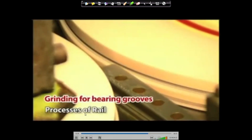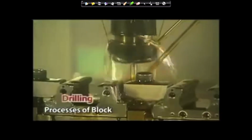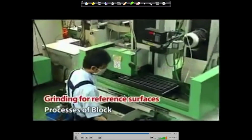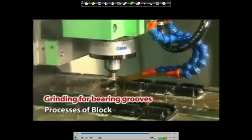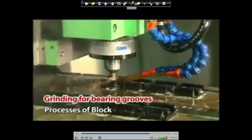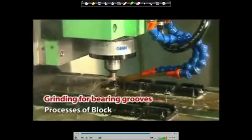Right. So, this is the processing of the rail, and we have to do the same thing for the block also, because we have to mount one block on the top. Again the drilling and all the operations are the same, and again you have to create the reference surface, because both are matching parts. What we discussed earlier was for a single component, but if two components come into contact with each other, you have to create a reference surface for the other one also.